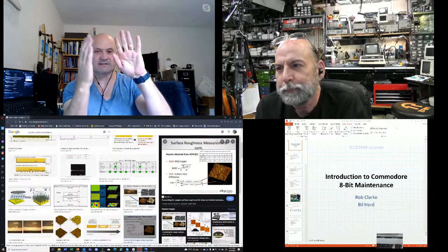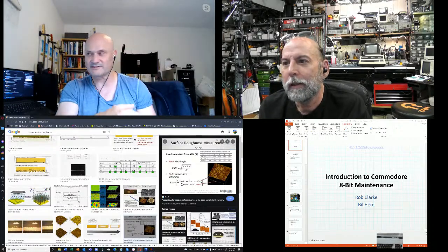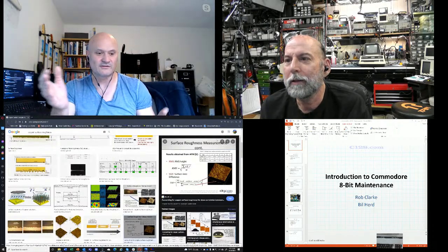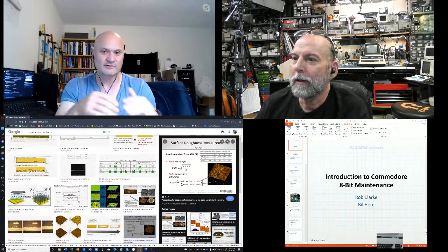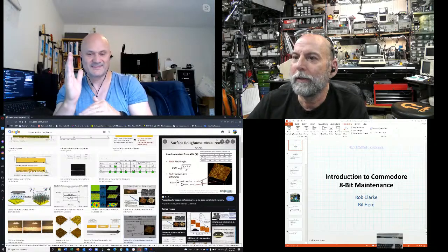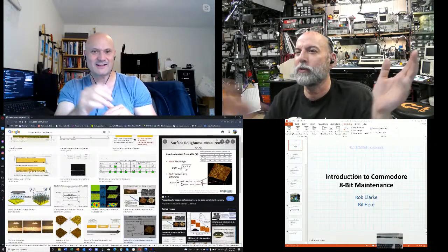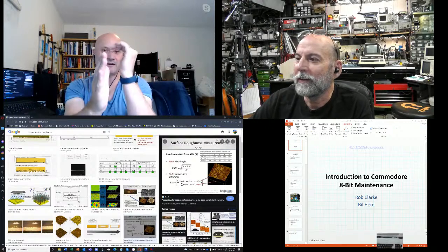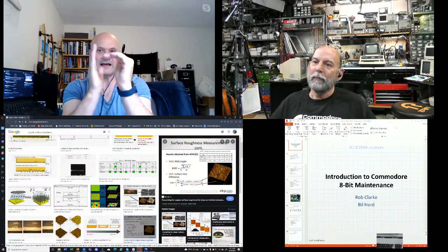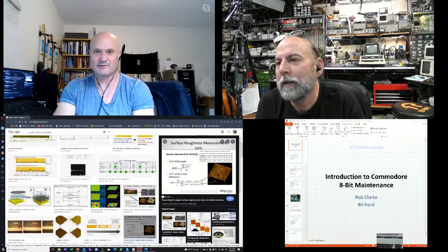And then we've talked about this before so many times. Even with the C64 and C128, you had to run that extra wire on the C128 because the hold time couldn't hold it. Right, reflections were showing up. Yeah, so you have to hold it so that the clock happens. When the clock happens, it's sampled in a stable 1 or 0.